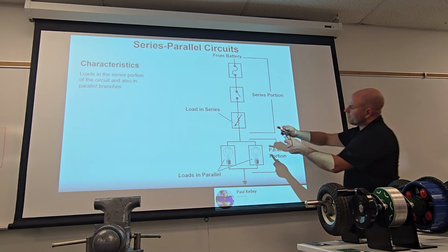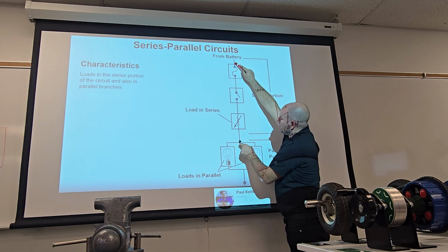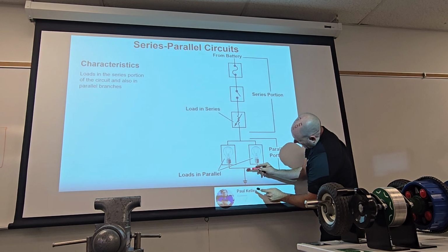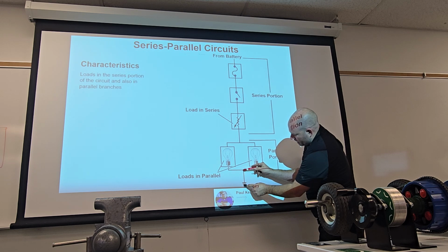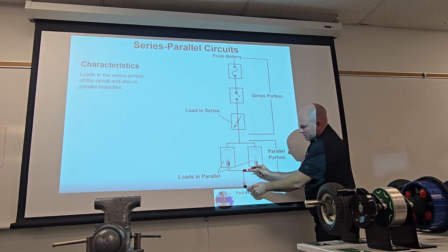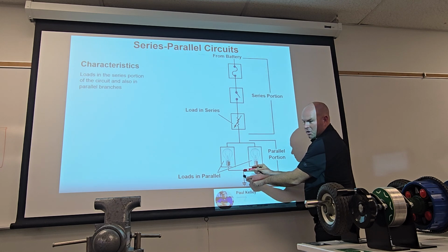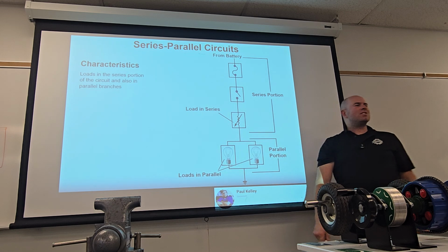No, let me do it one more time. Look at right here, I'm before the load. Right here it drops 0. Now I'm after, right here it drops 12. Look at my leads. I'm dropping 12 between what 2 points? So the problem is on which side, the positive or the negative? Yeah, that's what I'm saying, right?